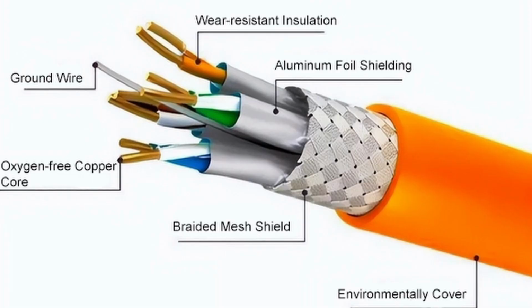One of the main assembly level changes that you can make is to use a shielded cable. I don't want to spend an entire additional 30 minutes talking about the theory behind shielded cables, so I'm going to save that for a separate video. But the key takeaway here is that a properly shielded cable can significantly reduce your common mode emissions. The way it works is that it ensures that the common mode currents travel along the shield of the cable and not the actual conductors that are in your cable assembly.